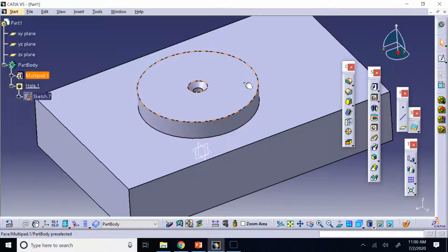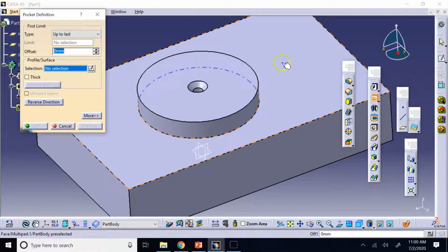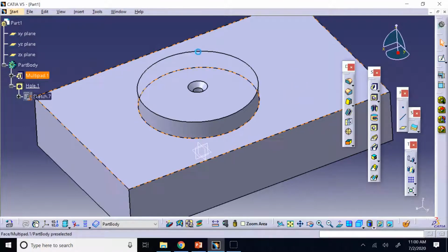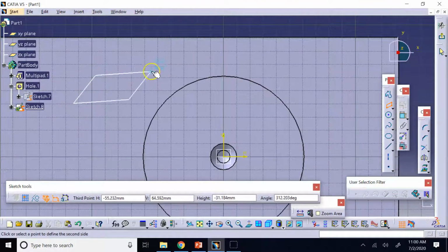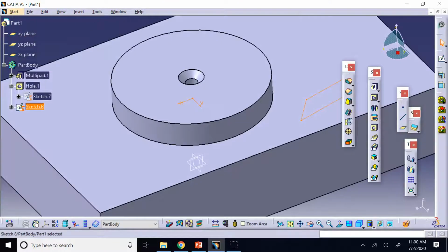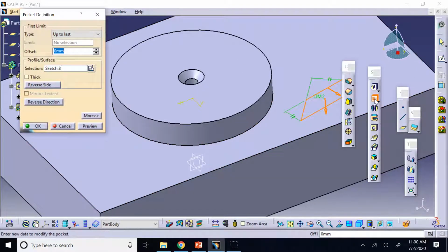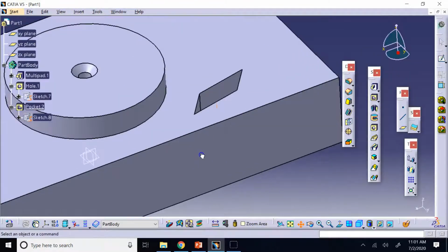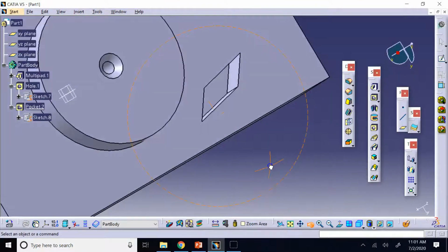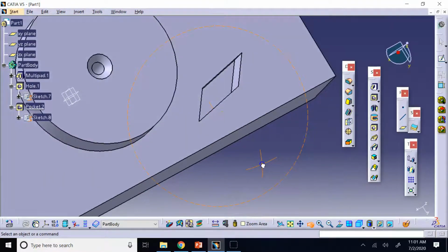Since that is an important point, let me just tell you, if you want this object to be created, okay, and then you go on this surface and let's say you draw any shape that you want, okay, like a parallelogram, like that. Get out and cut extrude this guy. Okay, so yes, you can create this fancy feature inside the object like that, a parallelogram cut.